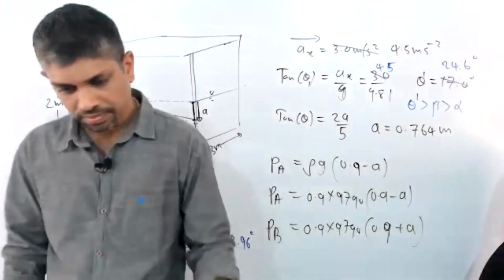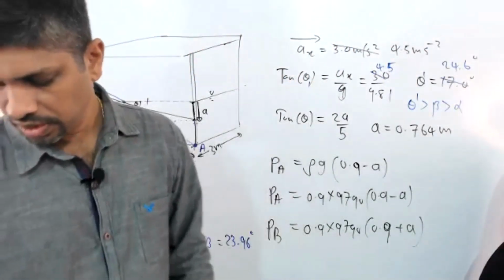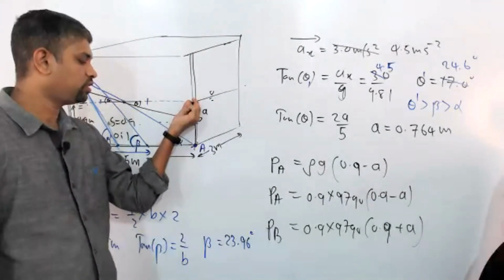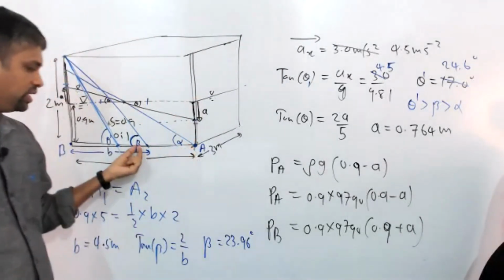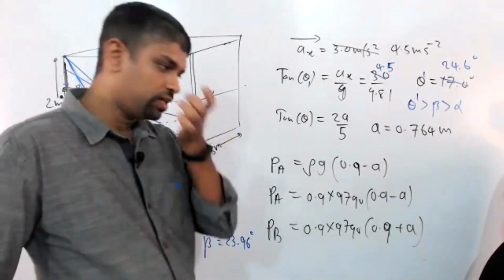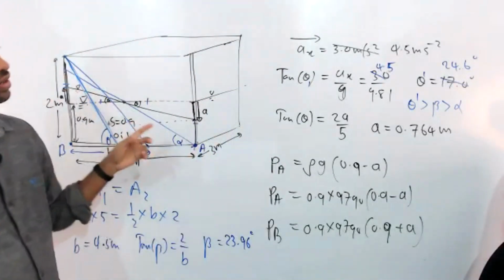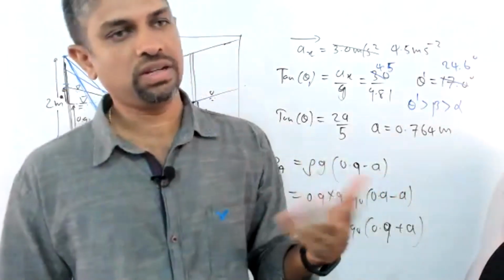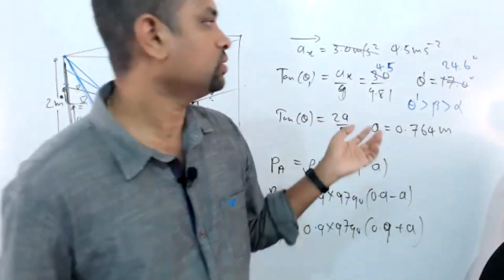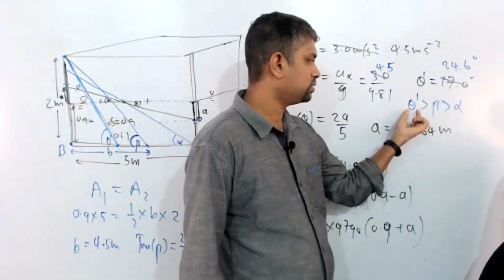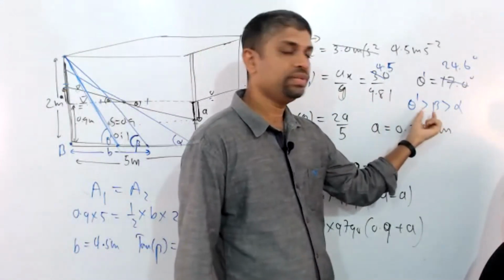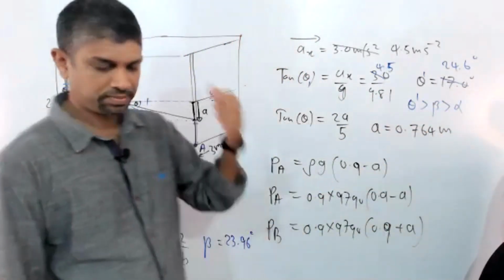Any problems? So alpha is the limiting point to touch the bottom of the tank. Beta is the limiting point to touch the top of the tank. In this case, the question is given, you have to calculate the amount of spill. We know definitely it is spilling, but you have to judge based on beta. The inclination is now greater than beta, that's why the water is going out.